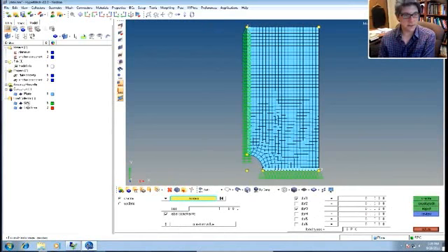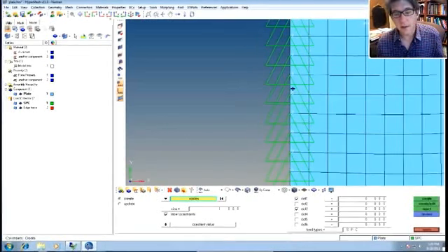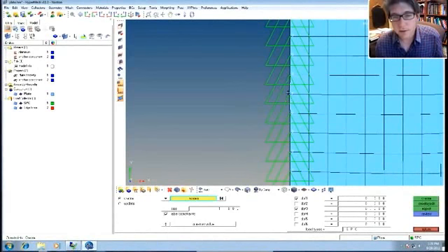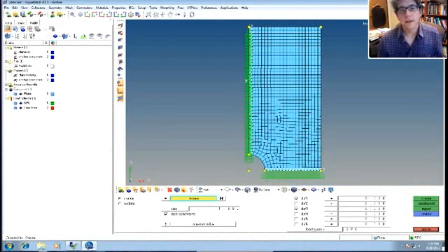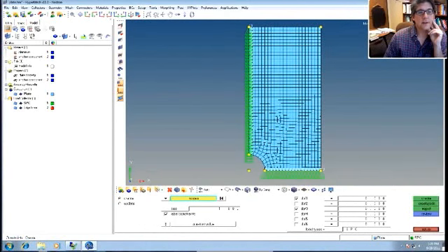They're still in this load collector, even though they have different values. You can see here, if you zoom in on it a little bit, we do a control and then middle mouse button, and we can draw a little zoom window, and you can see they're all set to 1, 3, right? 1, 3. I can toggle the view on and off, just to check that they're all in there. When they're green, that denotes that they're all in that layer as well. All right.